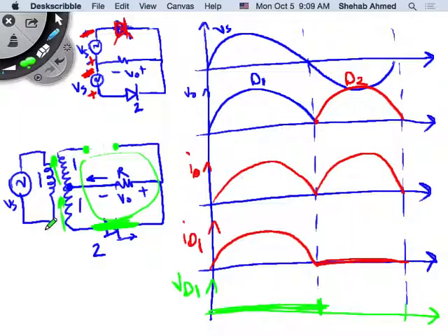No, remember, for voltages and currents, when we're solving circuits with Kirchhoff, instantaneously the value of the voltage, yes, is negative in the negative half cycle, but we have to assume a certain polarity and then calculate and see if it's positive or negative. If it's positive, then it's in the same polarity. If it's negative, it's in the opposite polarity, right? Maybe I confused you a little bit with drawing these pluses and minuses. It was just to show which diode can conduct, which diode cannot conduct. But if you're doing Kirchhoff voltage law around the loop, you cannot change the polarity of the source between the positive half cycle and the negative half cycle, right?